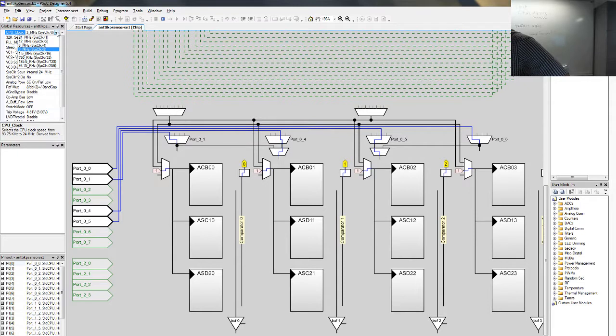On the power consumption level, how do you achieve low power consumption? You don't operate slowly, but in sprints. As fast as possible means you spend very little time doing the work, and the rest of the time you should be sleeping. That's the way to do power consumption.